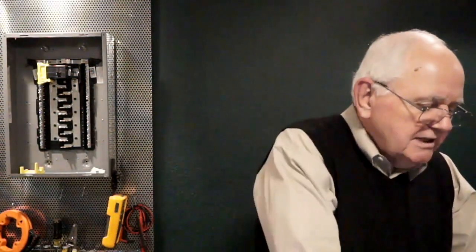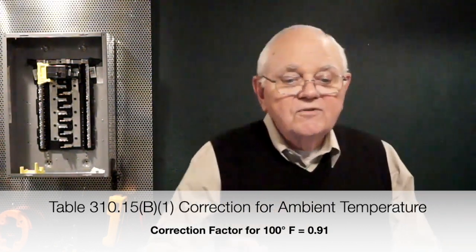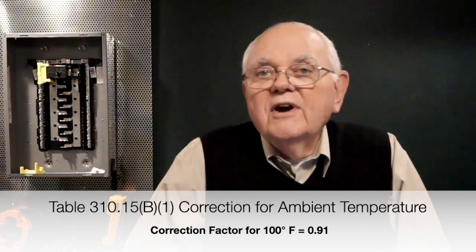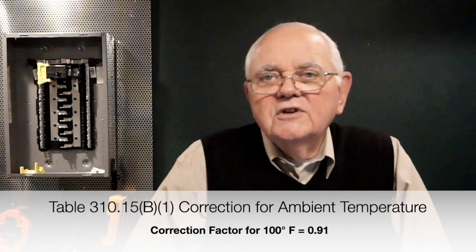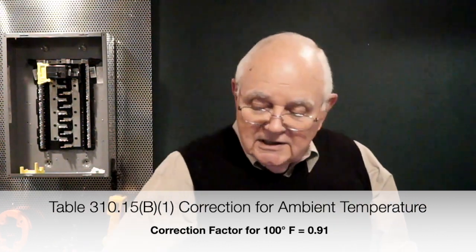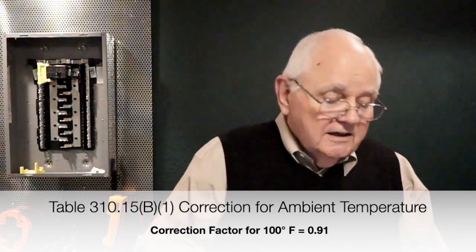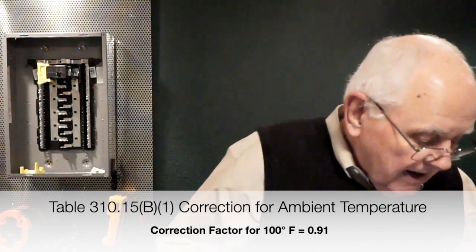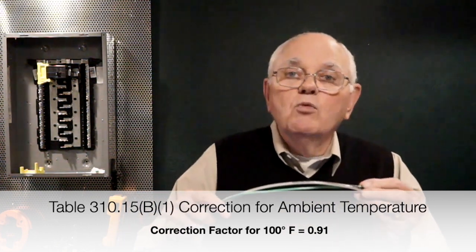So in this case, I go back in the code book to Table 310.15(B)(1), okay? It's for correcting for ambient temperatures other than 86 degrees Fahrenheit, 30 degrees C. So, for instance, if 100 degrees Fahrenheit is my ambient temperature, it tells me that my correction factor for 90 degrees C conductors would be 0.91.